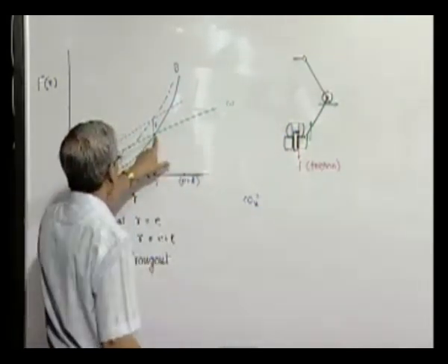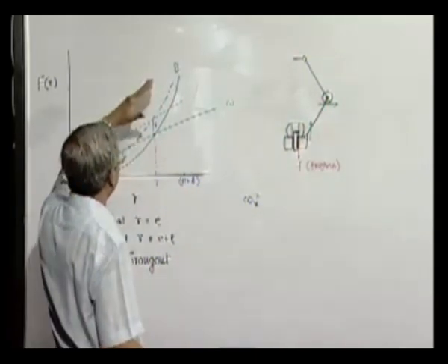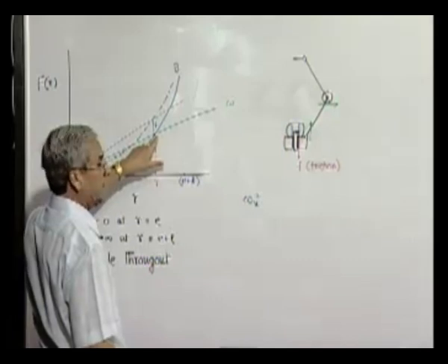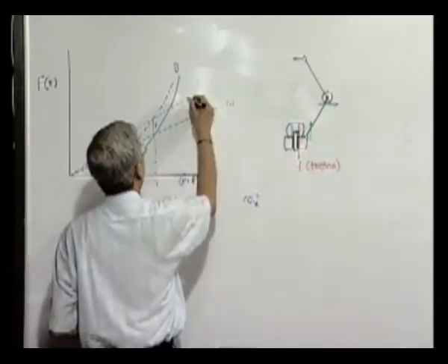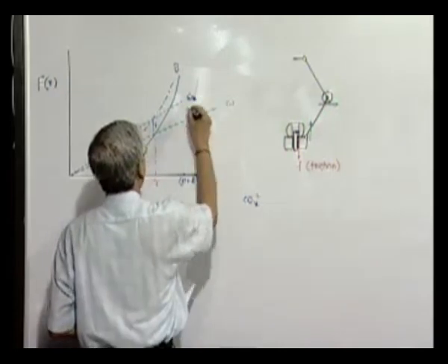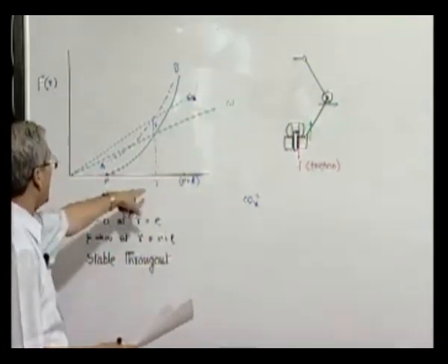So, at this radius, when the governor is rotating, the maximum speed at which the governor can still be at this location is this point. So, this will be your upper limit of the speed at which the governor can remain at this radius r.